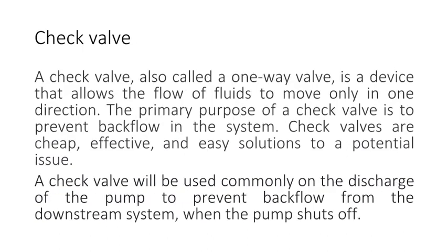Check valve. A check valve, also called a one-way valve, is a device that allows the flow of fluids to move only in one direction. The primary purpose of a check valve is to prevent backflow in the system. Check valves are cheap, effective, and easy solutions to a potential issue. A check valve will be used commonly on the discharge of the pump to prevent backflow from the downstream system when the pump shuts off.